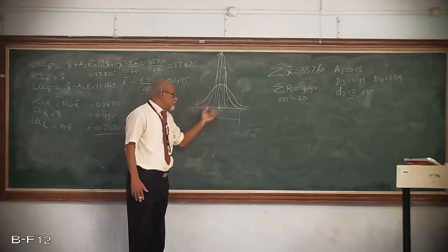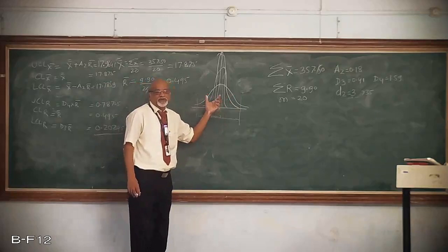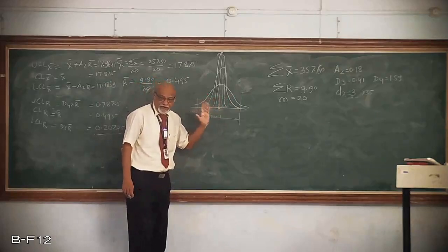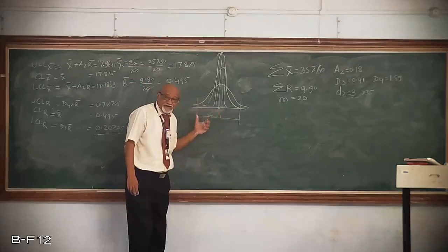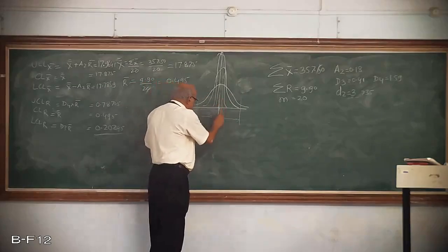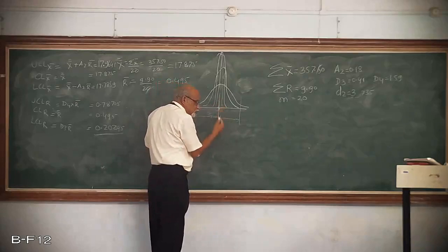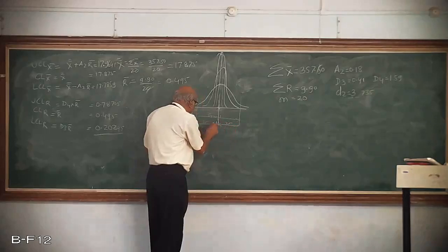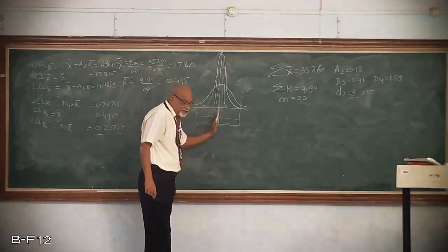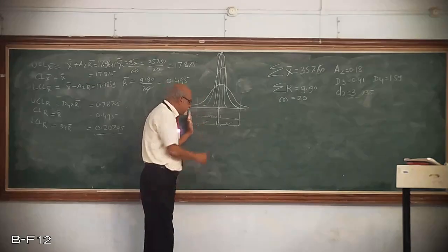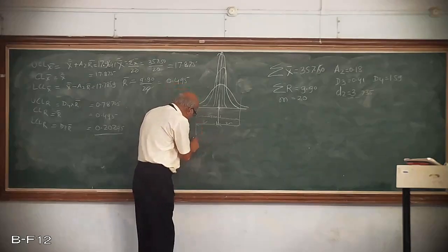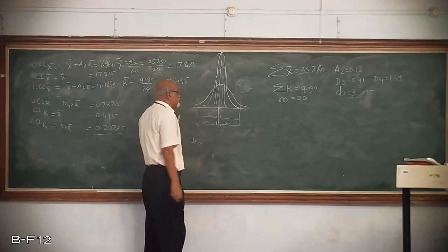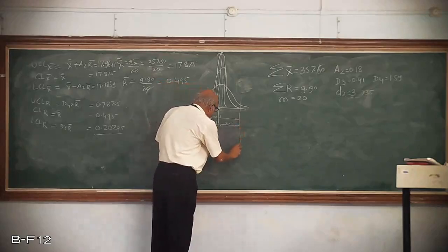But it has got some natural tendency. That is what is called process capability. What is its natural variation? This variation I can take up to the 3 sigma limit. So this is the mean value. This side it is 3 sigma, another side also it is 3 sigma. This 3 sigma is on the left side. The variation from here is mu minus 3 sigma, and if I go to this one, this will become mu plus 3 sigma.